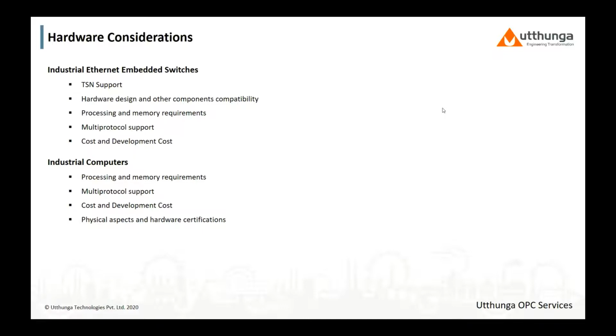And there are some industrial computers. These are useful for gateway type products where, on one side, it is OPC UA, and the other side is any of the industrial Ethernet based protocols. You can run your own software inside them, but hardware wise you will not have any options. So you need to look at whether it can be white labeled as per your company branding and that type of aspect, because there is nothing much for you to worry about there.